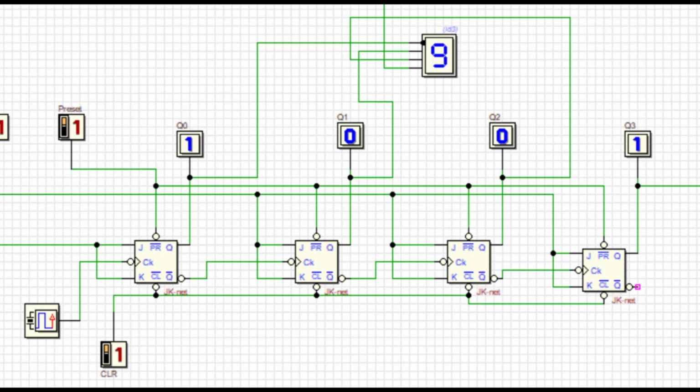Let's make the simulation a little faster. Again F. So this is a down counting circuit, with only a small difference: we have used a negative edge triggered clock pulse. Similarly, if you connect Q as a clock to the next flip-flop, it is going to count in the upward direction, which we will see in a moment.